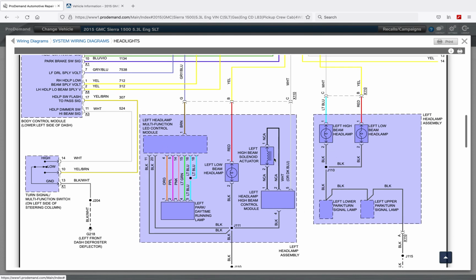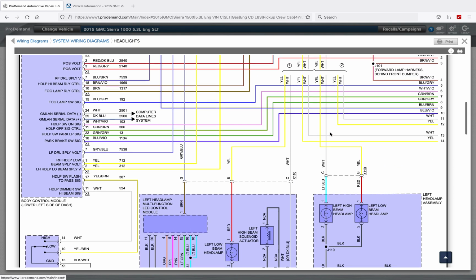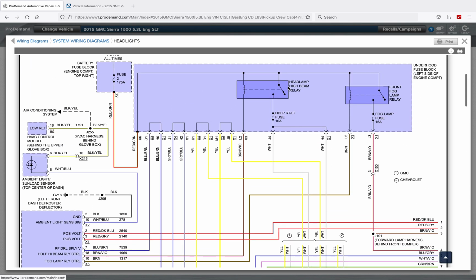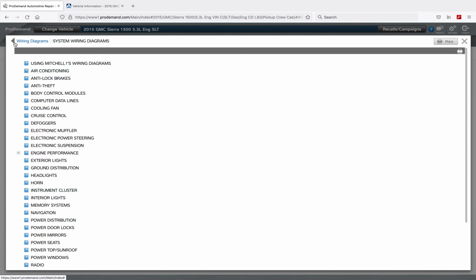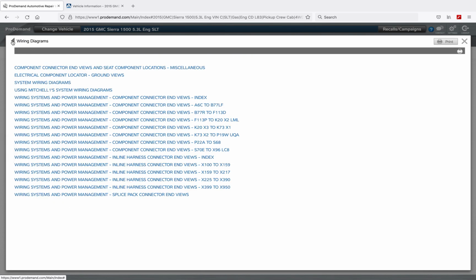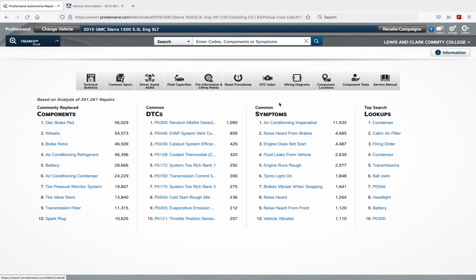This diagram within service information is going to give me leverage to walk through the process. Hey, what is this X10 connector on this vehicle? What is this white wire on this terminal C going to indicate to me that's light blue when I go to this left high beam headlamp point? Should I have voltage here, yes or no? If I use the diagram in its layout, when I turn this relay on, I should see voltage down here. So a little bit of a difference between the two types of service information we get that are commonly found in the aftermarket, but both of them are going to be beneficial for us.